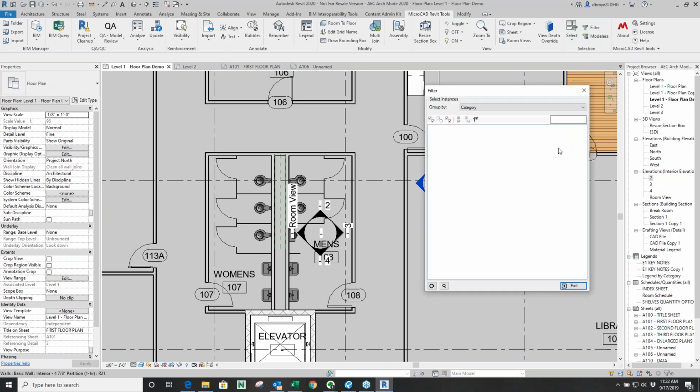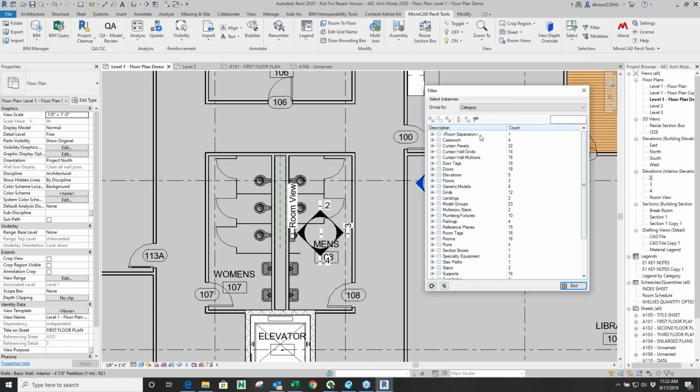Yes. So if we go here to the model list, and as we can see here, group by, you can also select by work sets. You can select by levels, rooms, space, families. It's a really, really great tool. So let's say I can select all of the doors on the first floor, or whatever level, or undefined levels.